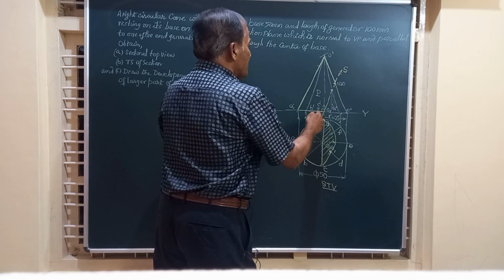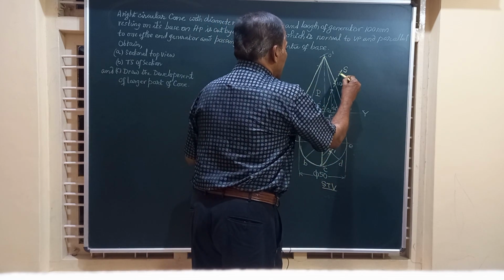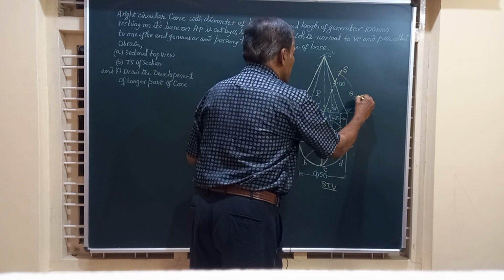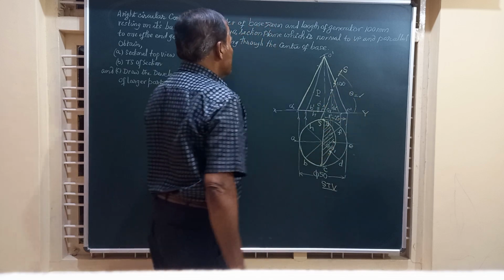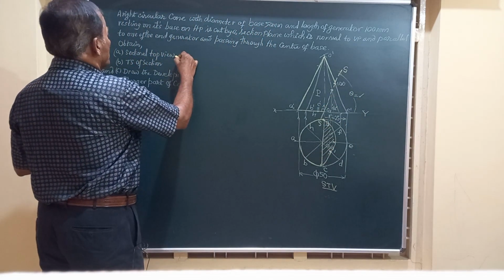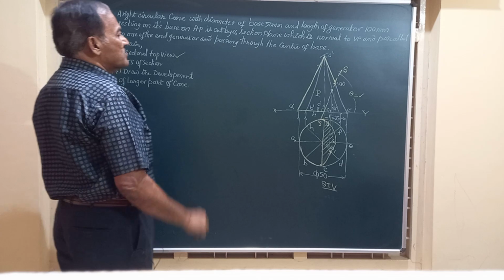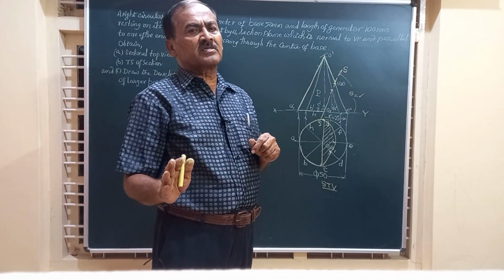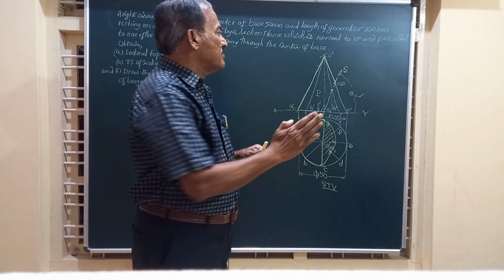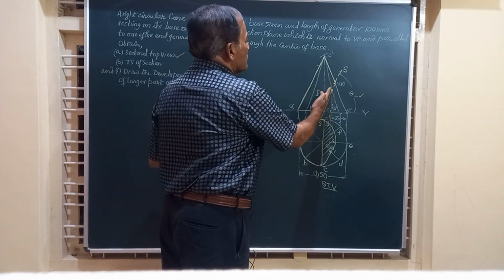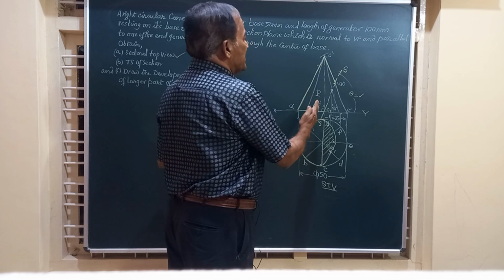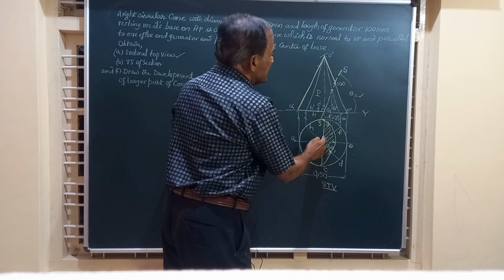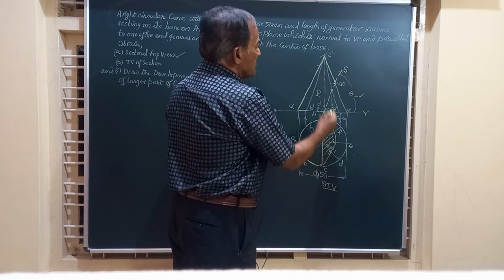This will give you the front view, and if you want to measure the angle made by the section plane with HP, that can be measured between these two lines. So you have got the sectional top view, and we want the true shape of the section, friends. The true shape of the section is the mirror image where this is being cut here. So friends, that true shape is going to be a figure similar to this.